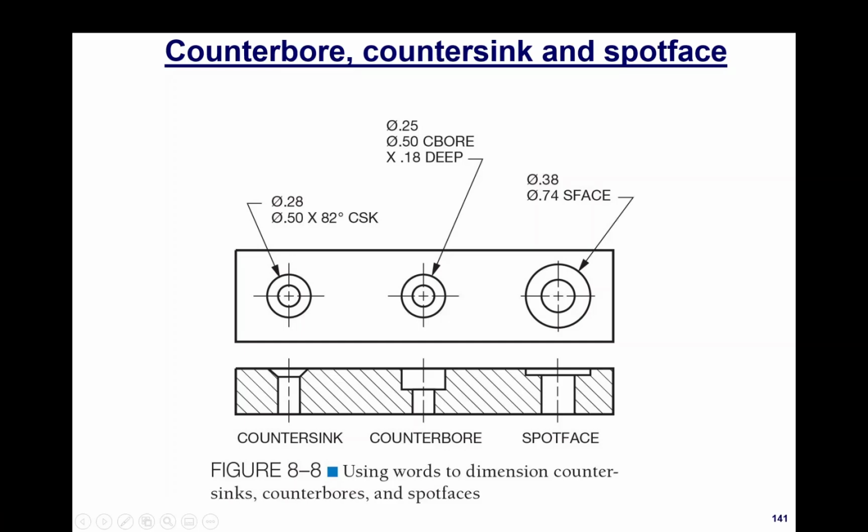The other feature, and I'll just circle this here, is called a spot face. A spot face is the same geometry as a counterbore, but it is shallower. It's not typically as deep as a counterbore. And you might say, well, it's the same thing as a counterbore, because it is. The geometry is the same, just a cylindrical feature. But it is a feature that's not controlled by specifying a depth.